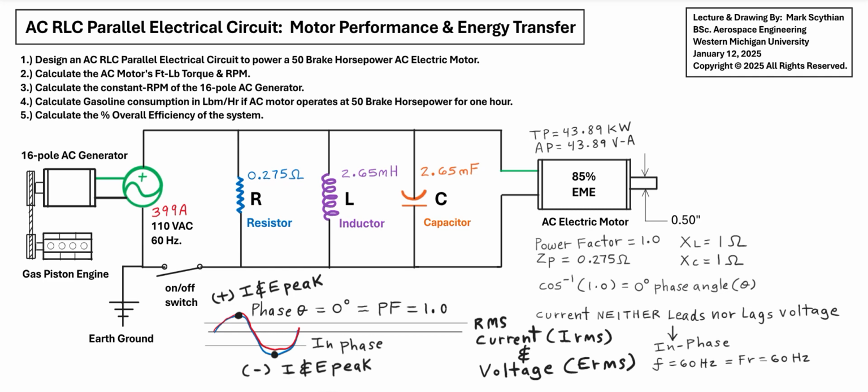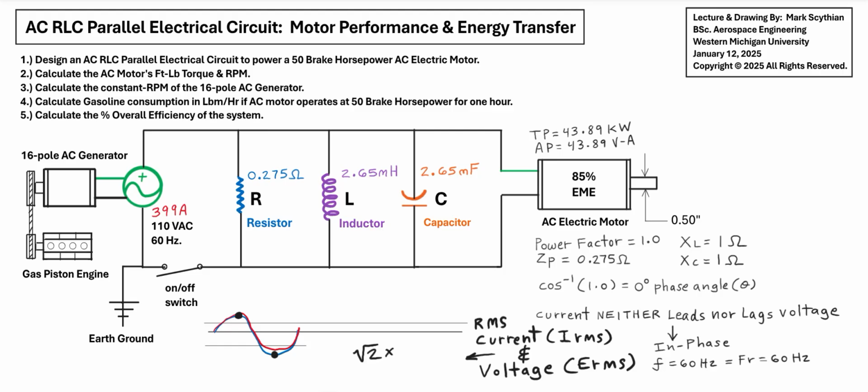But if we take 1 and divide it into the square root of 2, we then get the opposite, the inverse of 0.707 times the peak value to equal the effective. That is also equal to the cosine of 45 degrees, or 0.707. So just to make it practical and simple, we just take the square root of 2, 1.41 times the peak value at the top and bottom, or the crest and trough of the wave, and this will equate to the effective voltage and current values.